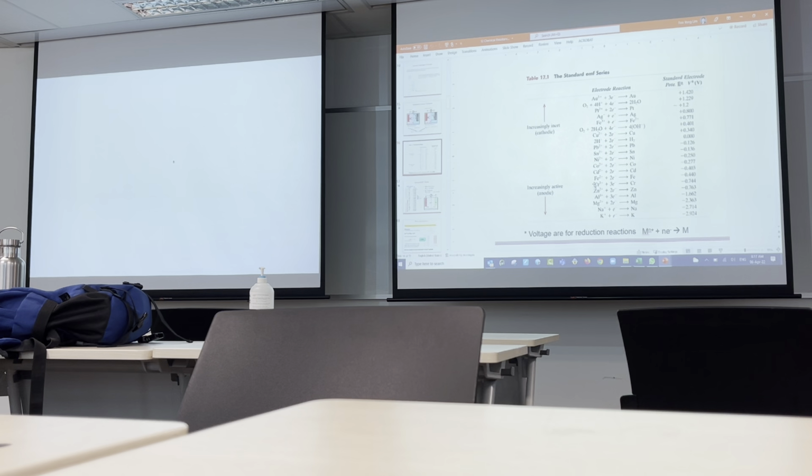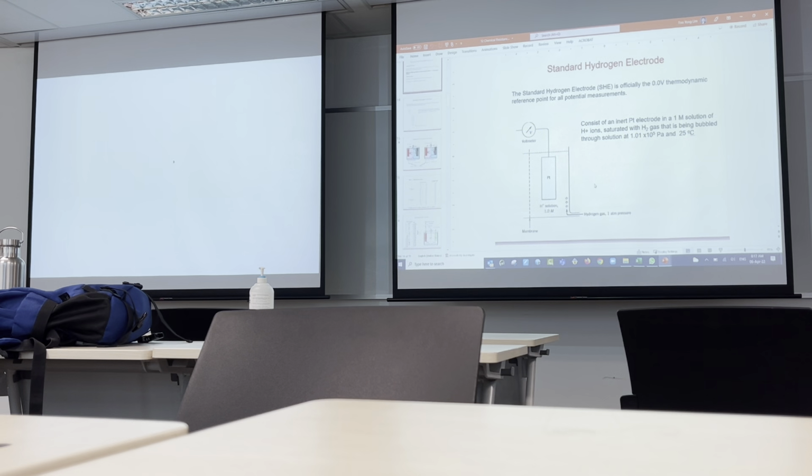One wants to give and one wants to consume. The one that gives has to become an ion in the liquid. In a simpler sense, a piece of metal, which is a solid, wants to dissolve in a liquid, meaning it corrodes. The other side will be electrodepositing. So the corrosion will be the one that actually sheds material, and the other one you can do plating. If you want to plate gold or nickel, electroplating, then you know what is on the other side, the counterparty. So this is the gist, the whole idea of corrosion.